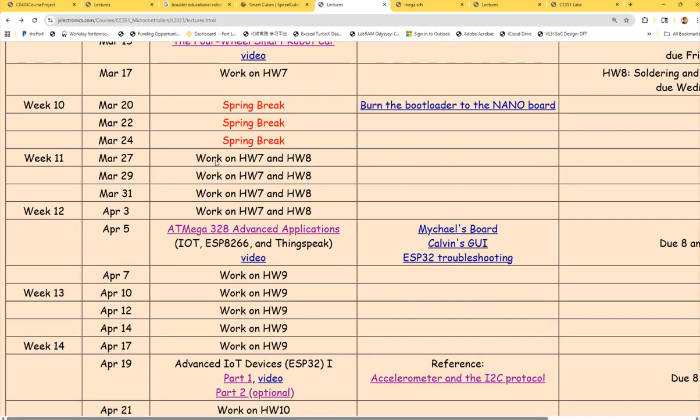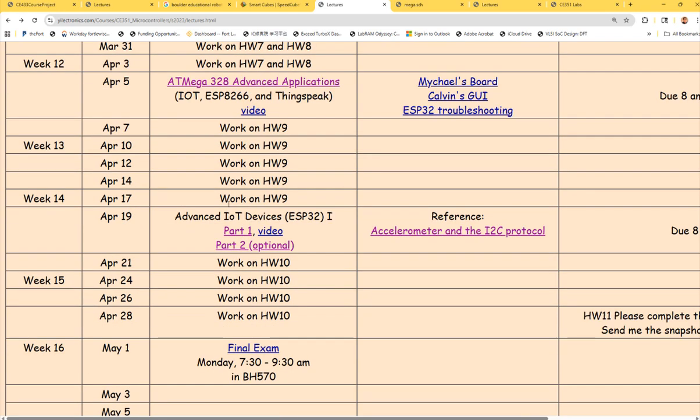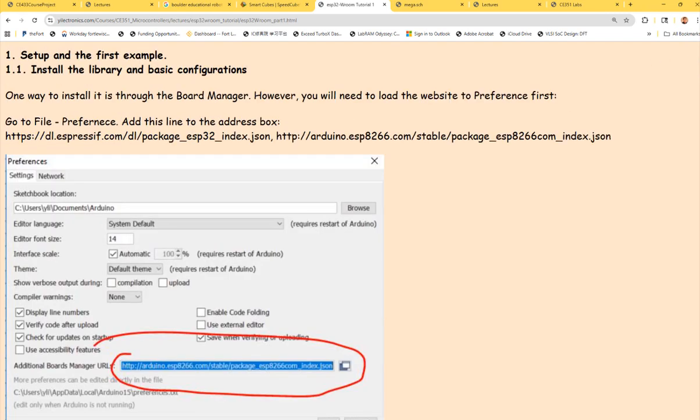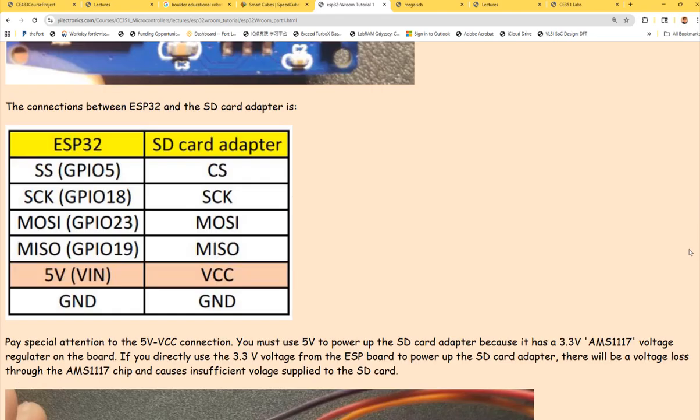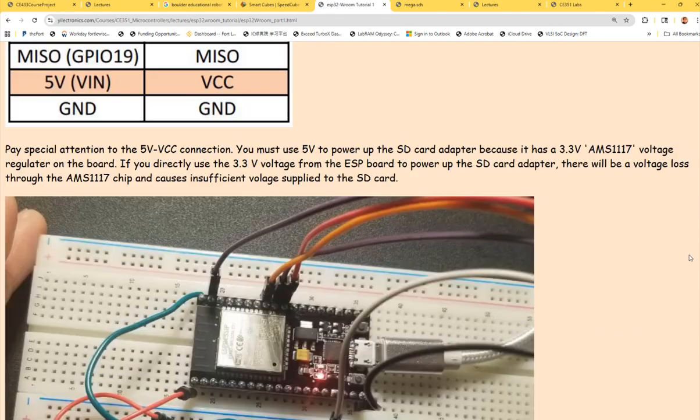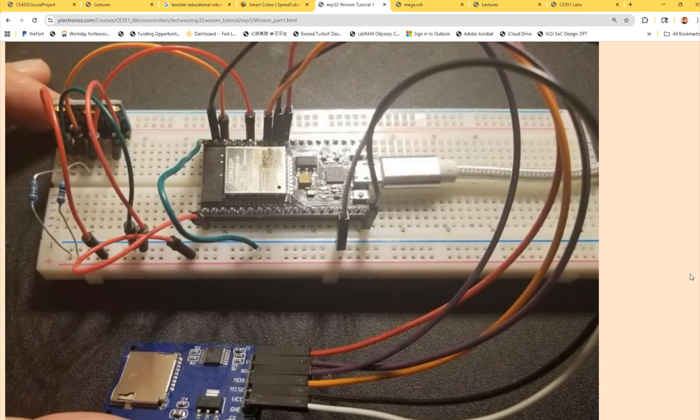All right, another project. And I also have different motors. This is the SD card module. This is the ESP32. It's another very popular microcontroller that I can code using the Arduino IDE. All right, so here's the chip. It already includes the microcontroller and also the RF stuff inside the chip. So you are not actually designing that PCB by yourself. What you need to do is just purchase this little module and solder it on your design.